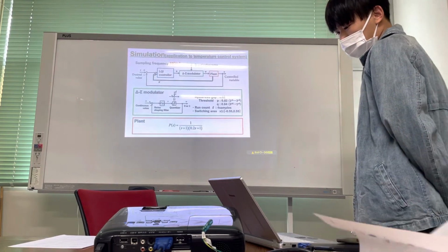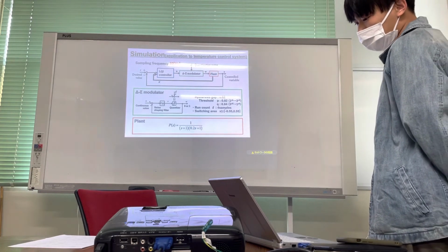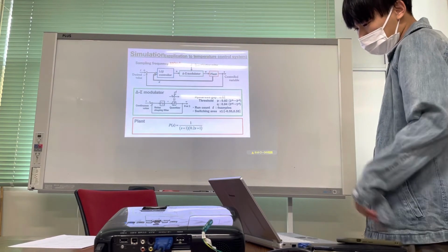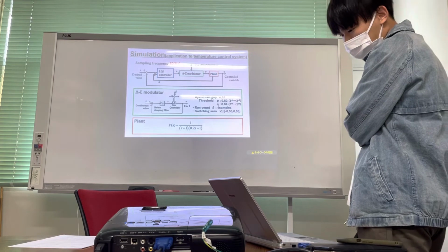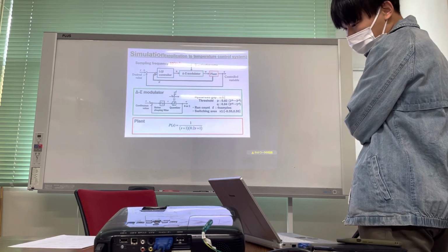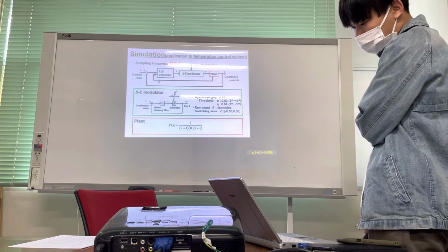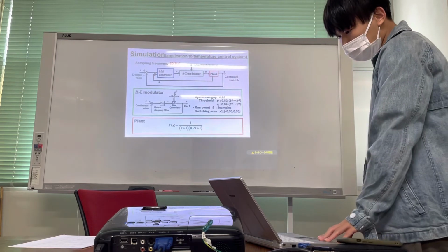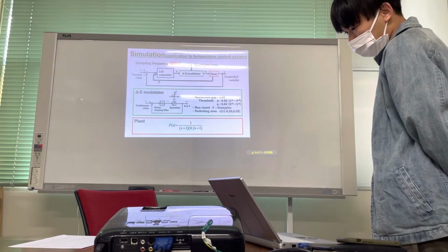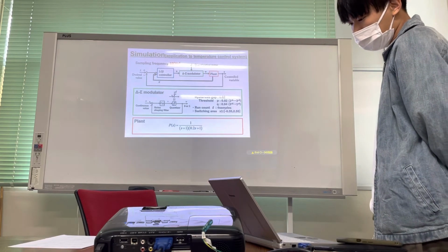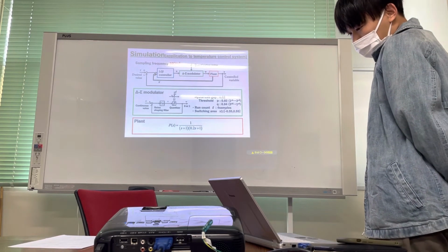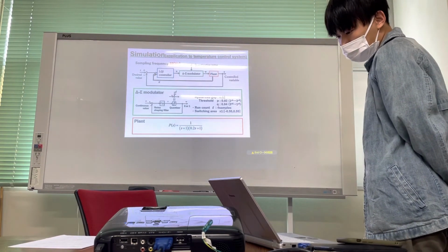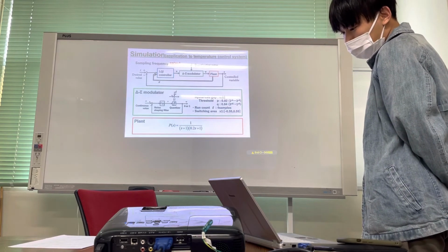A simulation example is presented to demonstrate effectiveness. Here is the temperature control system used for purification, and it is assumed that the heat source of the temperature control system is a halogen lamp with a short time constant. The control used an LQI controller and the sampling frequency used is 16 Hz. The controller calculates the power to supply to the heat source based on the feedback signal.